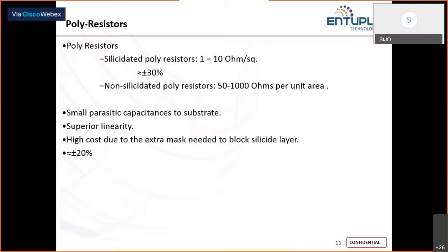So coming to the layout of standard resistors, what you can see is we mostly try to avoid 90-degree angles at the bends. We always look for a 45-degree or a curved shape. You can see the layout structure here. The first one has a 45-degree angle at the bends, and the other one has sharp 90-degree edges. The resistance at the corner cannot be estimated accurately.